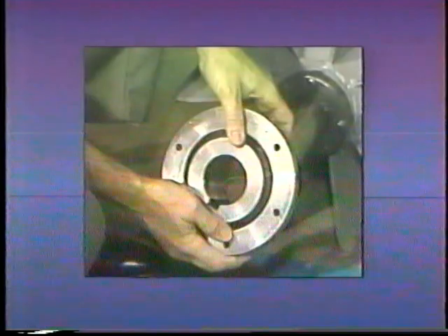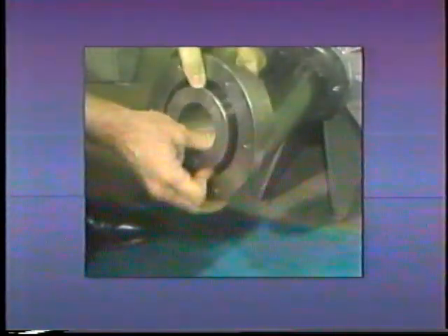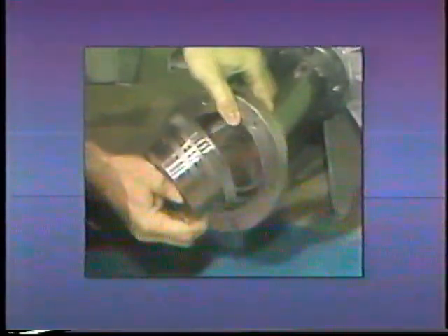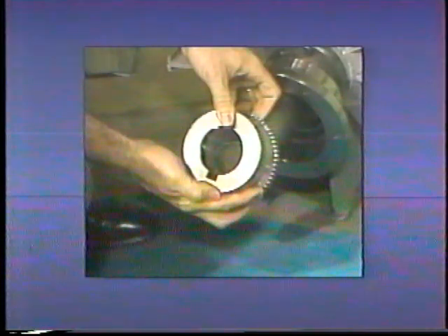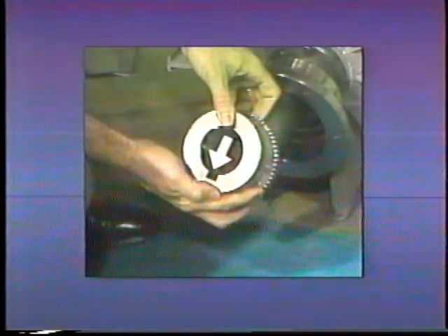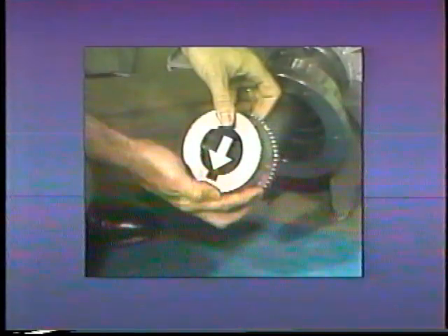When couplings are subjected to heavy shock loads, or when loads must be continually reversed, the slight movement between the coupling and the shaft can cause wear and eventual failure. To prevent this, some coupling manufacturers recommend interference fits, in which the hole in the coupling is actually smaller than the shaft it fits over. Usually, the hole in the coupling is 1/2 of 1/1000th of an inch smaller than the shaft for each inch of shaft diameter. A key is still used, but the interference fit prevents movement between coupling and shaft.